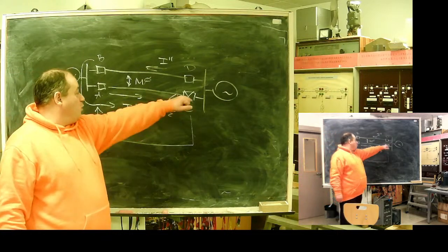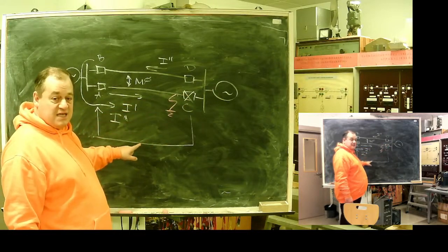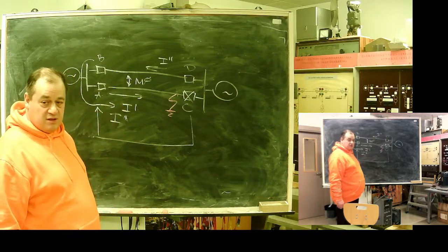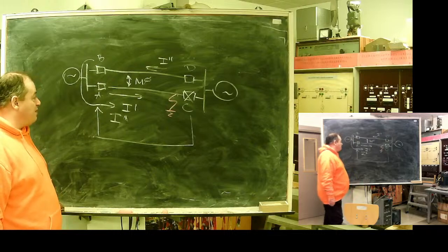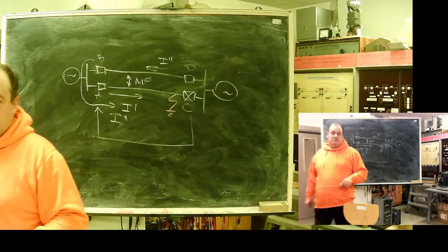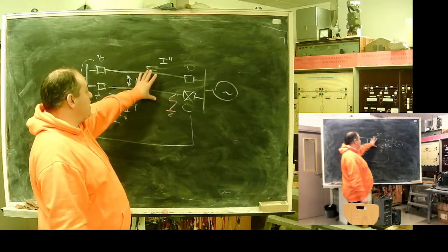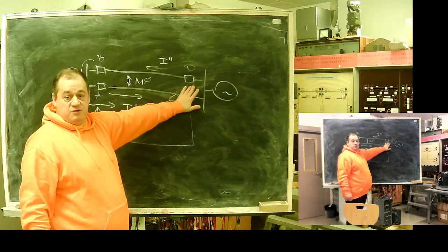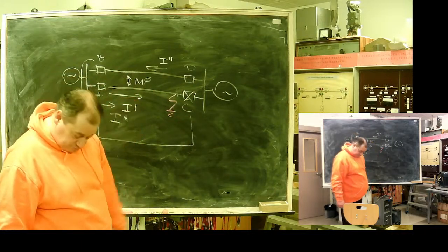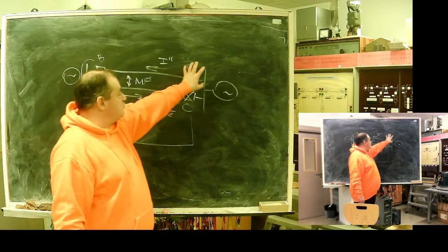So if one end disconnects, if you have communication network, signal to disconnect the opposite end is very welcome. And this prevents false operation of this relay. But check it. In such case, where you have parallel line, disconnection of the switch reduces observable resistance both for this relay and for this one.